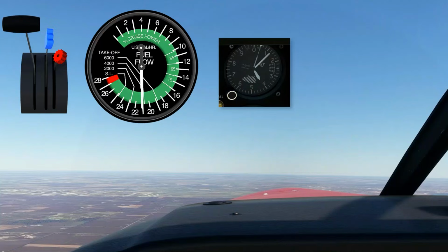First of all, your manufacturer may have a fuel flow schedule. Again, this is the Comanche, and it's marked directly on the fuel flow gauge here. We have markings for takeoff fuel flow, which is really just full power fuel flow, all the way from sea level up to 6,000 feet. And you can simply lean the mixture to match the fuel flow to whatever your altitude is as you climb.